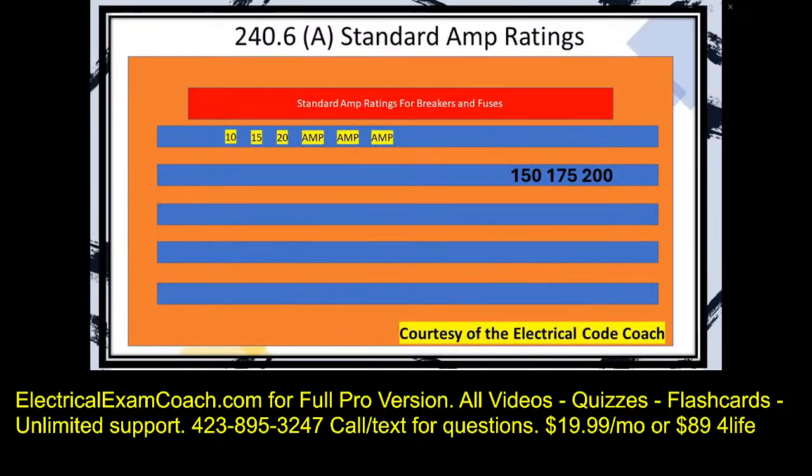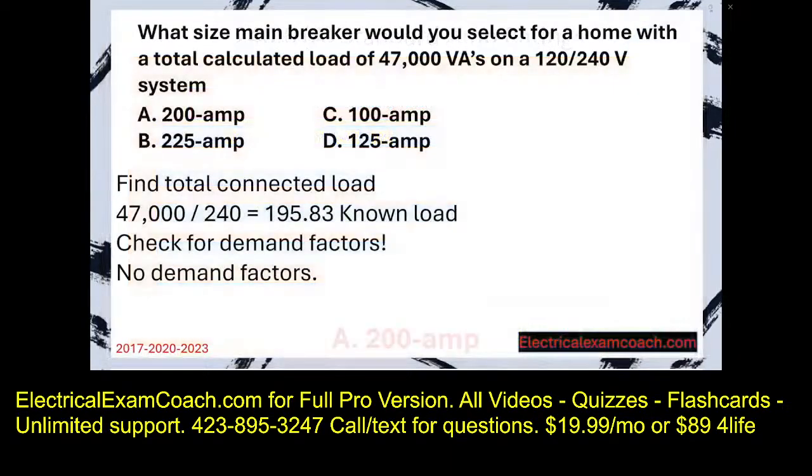Now we head to Table 240.6(A) and choose our next standard size. And in this case, it ends up being a 200 amp breaker. Great job!